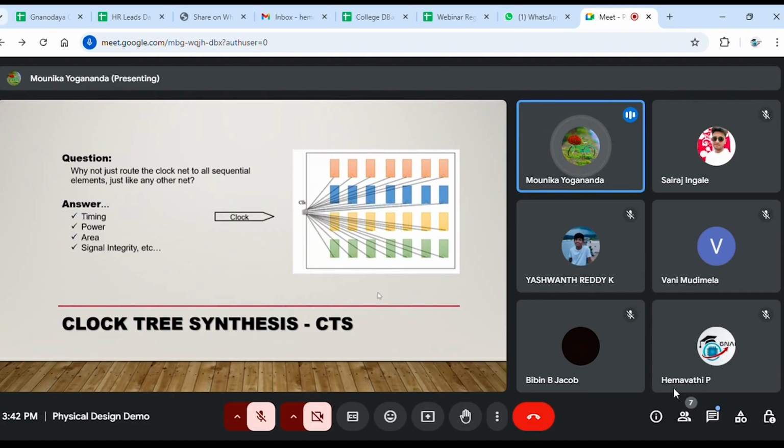From now onwards, you are going to see the clock information, like the clock tree, how the clock is splitting to all the registers in your entire block, how much timing it has taken, any noise it has introduced while the clock is distributed, and how much utilization has jumped from placement to CTS. Those are the things you are going to see. Up to here you are going to know only the logical, that means your imaginary view only.